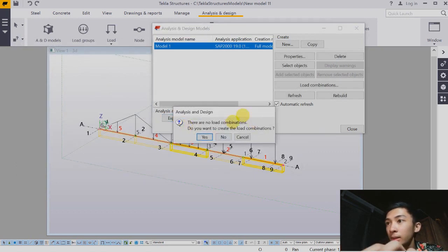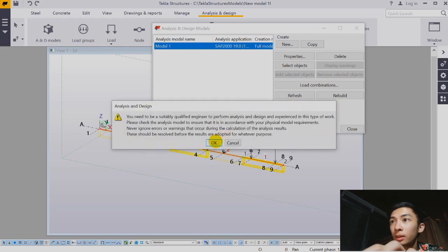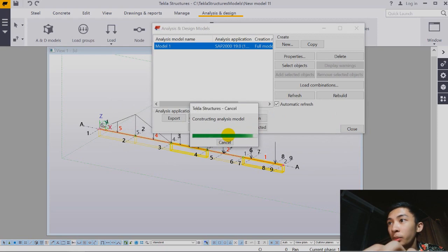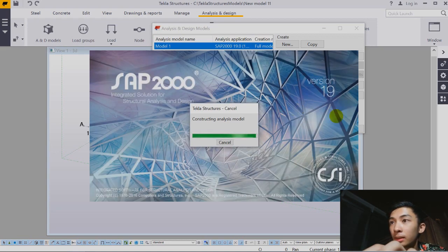Then let's change the connection of the beam. Click the beam, then click get analysis properties. For the start analysis tab, this should be fixed connected, and for the end analysis, this should be fixed connected also. Click modify, then click the next beam, click modify, then the last beam, click modify, then OK.